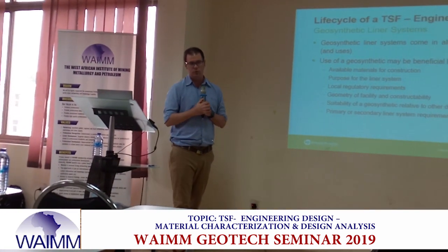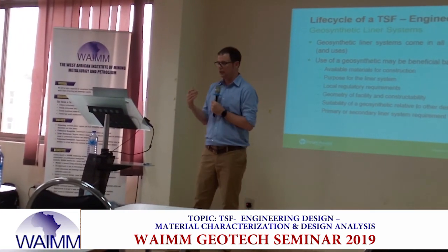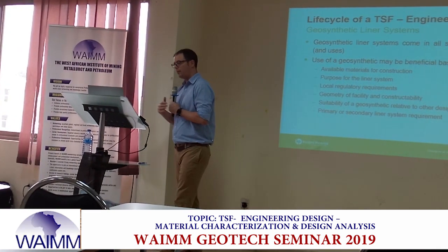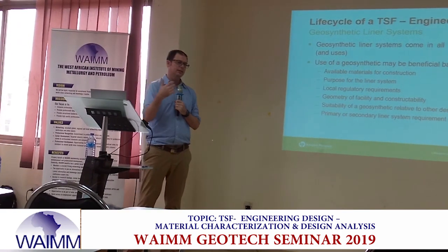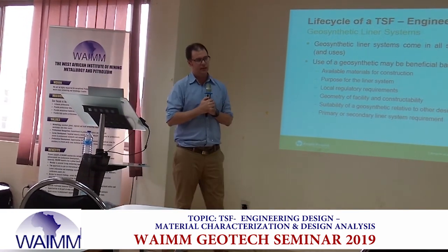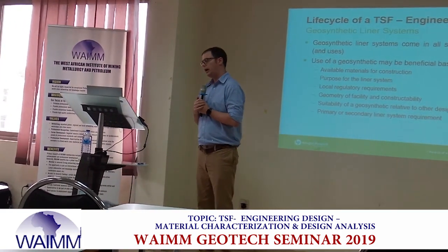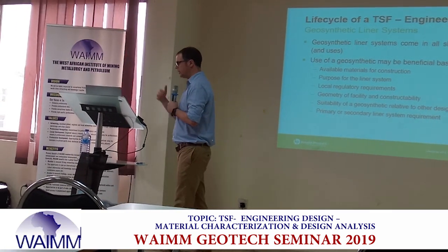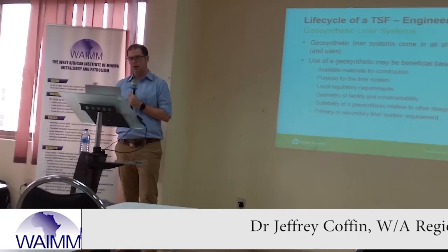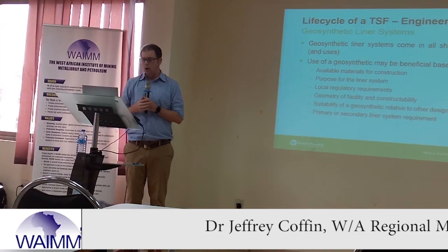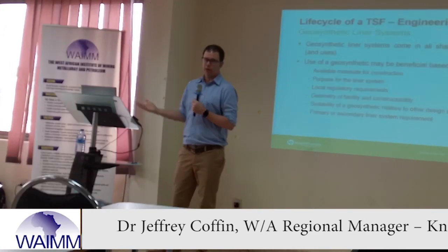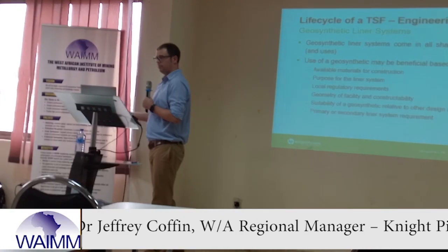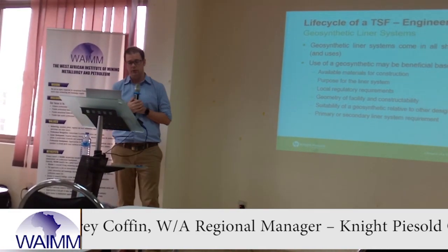Geosynthetic lining systems using a plastic, an HDPE, LLDPE. They come in all shapes and sizes and uses. We're starting to see more and more geosynthetics being used in Ghana for various reasons. We just need to make sure, again, that we're using the right products for the right reasons. Some of the benefits are availability of construction materials. If we don't have those low permeability soils, maybe we need to bring in a geosynthetic.